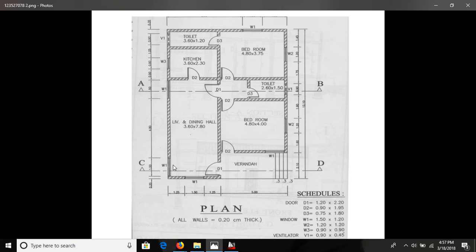Otherwise we can take a rectangle and make it the walls, and use the trim command to trim the unwanted things. But I'm not going to do it that way, friends, I'm doing it my way. I make the X partitions first and after that I'll make the Y partitions. Observe, finally it is 9 meters and 12.10 meters.